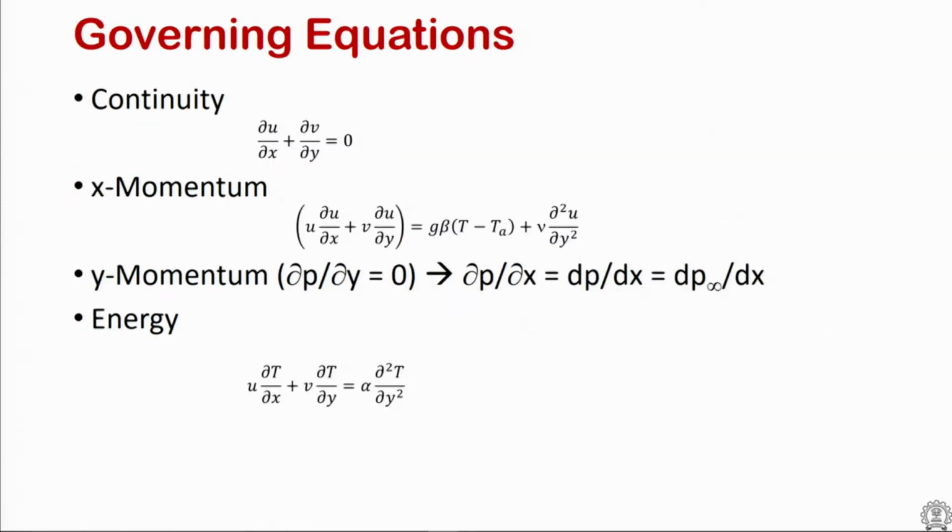If you look at the boundary layer equations for this, the gravity or buoyancy term shows up in the momentum equation, and it does not show up in the energy equation. I am sure you are well aware of that by now. In this case the gravity direction is pointing in the x direction, so that is why the buoyancy term shows up in the momentum equation.